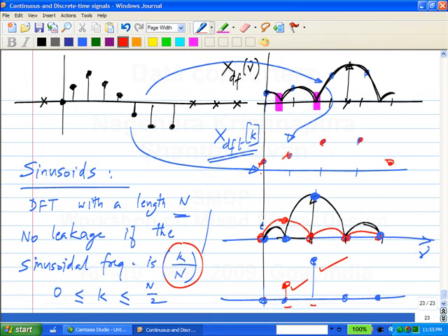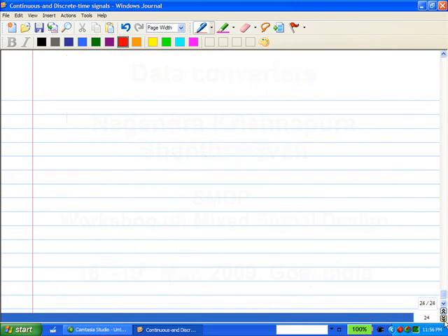The other possibility is where you are just doing analysis, like numerical analysis, when you are doing simulations. So when you are doing simulation of an A to D, you should also choose it so that it is k by n. That is, what I mean to say is, the normalized frequency is k by n. Okay. So what will be the frequency in real terms in hertz?